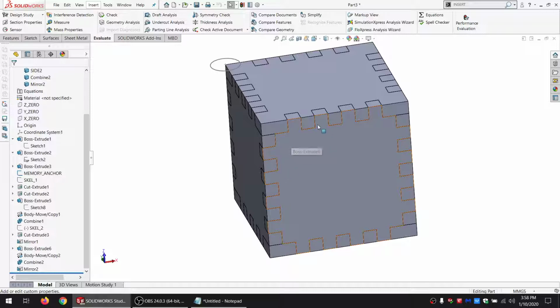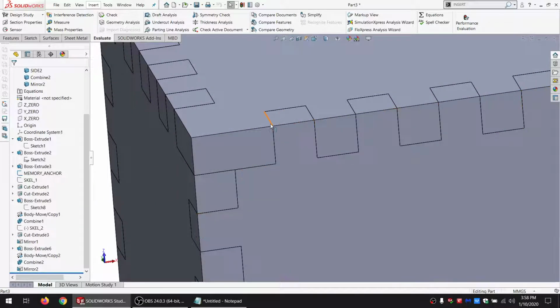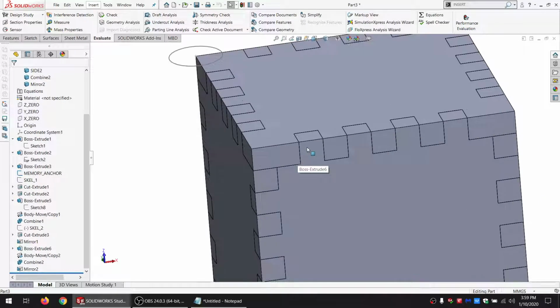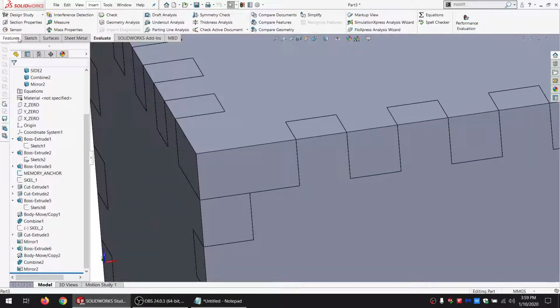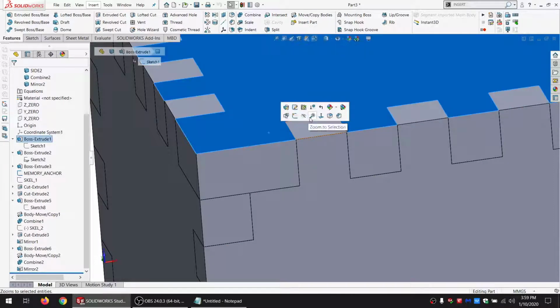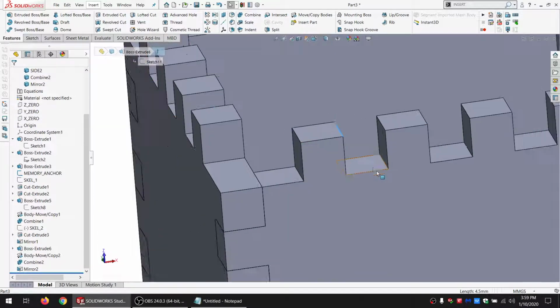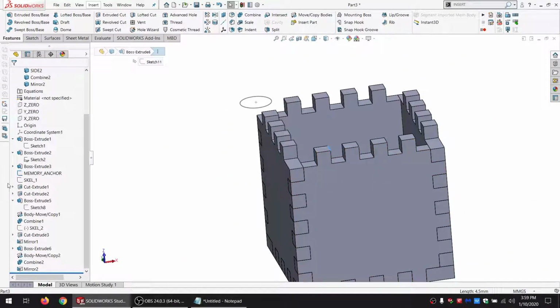The last thing is that with these fingers, a lot of times these hard edges are difficult to assemble. Just putting a little bit of a chamfer, like this tool here, on each of these edges, so there and there, and all the way down, it really helps with assembly.